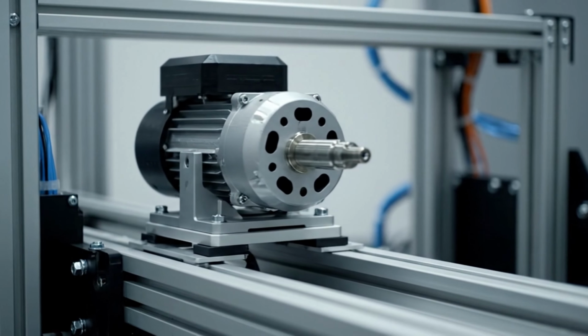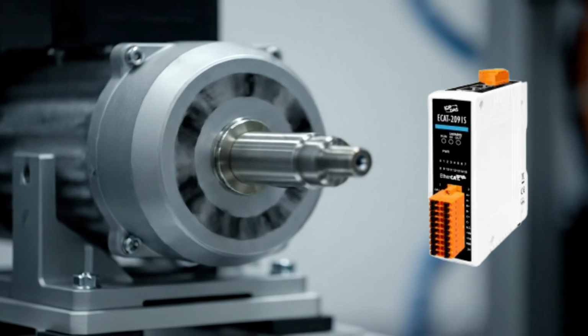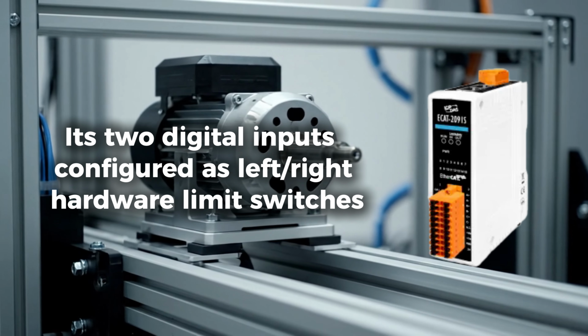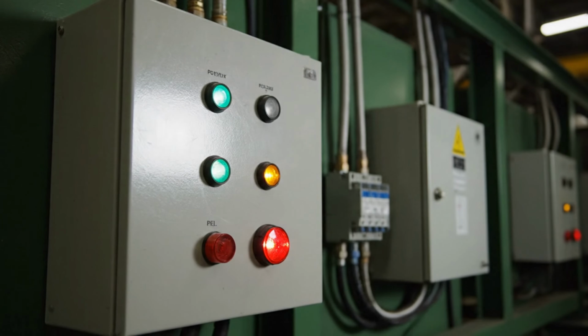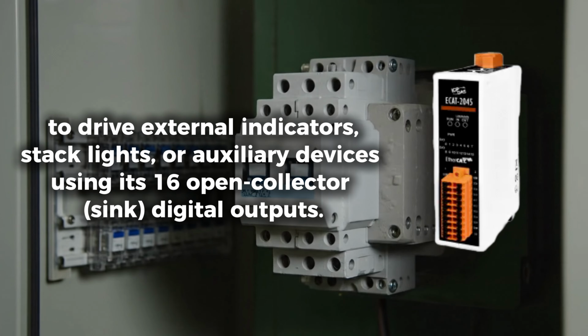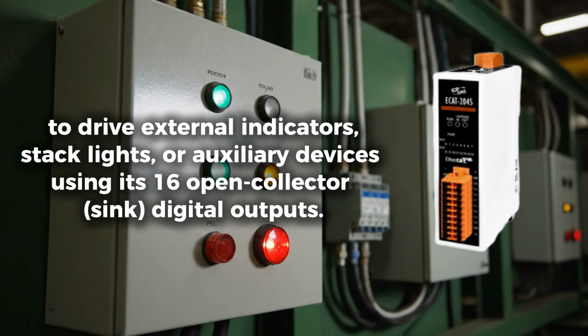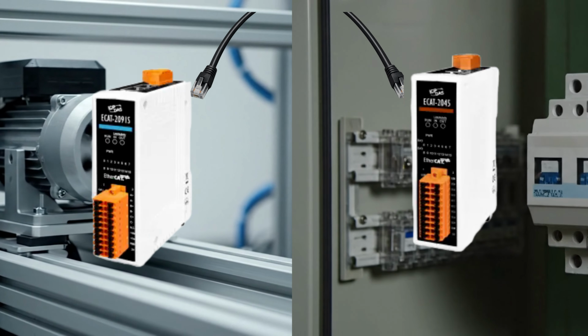In a positioning system, you might use the EtherCAT 2091S to control a 2-phase bipolar stepper motor, with its 2 digital inputs configured as left and right hardware limit switches, and a module like the ECAT 2045 to drive external indicators, stack lights, or auxiliary devices using its 16 open collector digital outputs. And that's how a realistic EtherCAT architecture is meant to look, with motion and I/O all on one deterministic network.